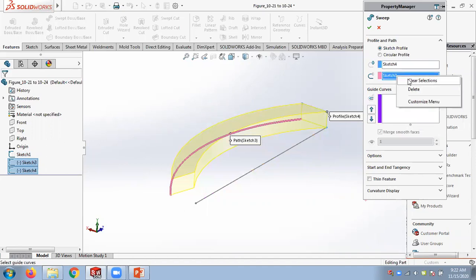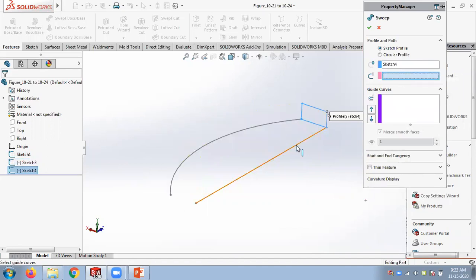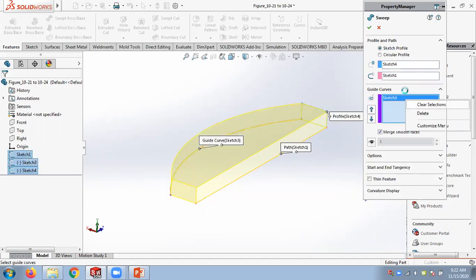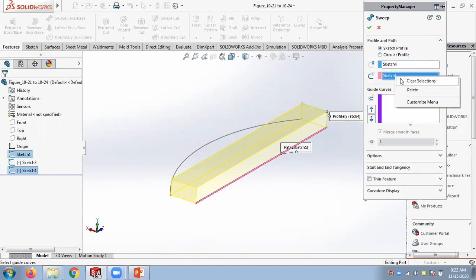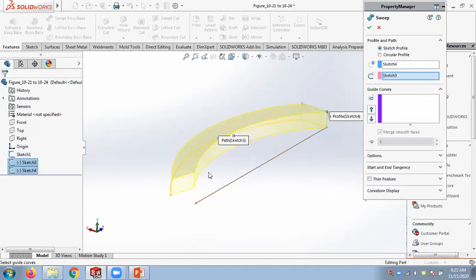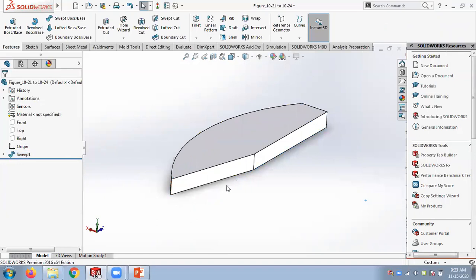If I just select this as the path, nicely it's finishing here when you use the guide tool. The other way it's not going to work. It's working, but it's not finishing nicely. So you can see with the turn how it finishes. So this may be an extra line. When you press OK, you will not see that extra line. So you can get this kind of output.